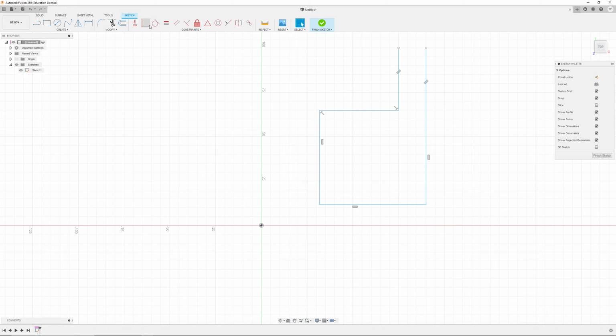So that's basically all coincident is, and it applies not only to lines but also to circles. So if I had a circle like this and I wanted a line that was on that circle, anywhere that circle goes, that point is staying on that circle. So coincident is used a lot. You will see it regularly, and we will even be talking about some advanced uses for coincident at a later point.